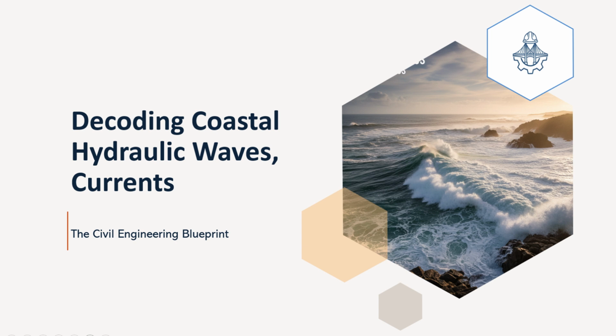While waves in deep water cause orbital motion but little net transport, as waves shoal, break, and run up the beach, their shapes and the associated water velocities become asymmetric. This asymmetry can create a net movement of sediment either offshore, typically during high-energy storm conditions with steep waves, or onshore, typically during lower-energy swell conditions with flatter waves, helping rebuild the beach.